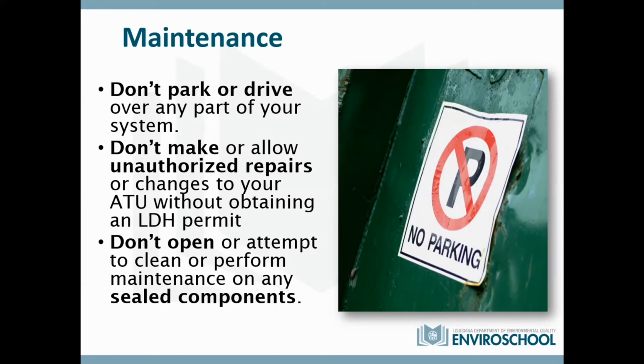Speaking of repair costs, do not make or allow unauthorized repairs or changes to your system without obtaining a Department of Health permit. Basically, the Department of Health regulates the approval of the type of system to use for your property, and any changes to that have to be run through them because that system is designed for what you're doing. Also, it says don't open or attempt to clean or perform maintenance on any sealed components.